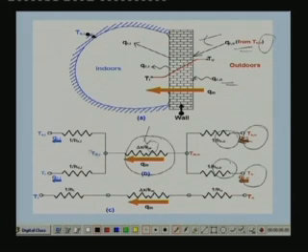And again from the inner surface to the conditioned space, that means to the indoors, you have heat transfer by radiation and convection. So you have radiation heat transfer and convection heat transfer. You can see here that again 1 by H subscript Ri is the resistance to radiation heat transfer inside the conditioned space, and this is the resistance to convective heat transfer.